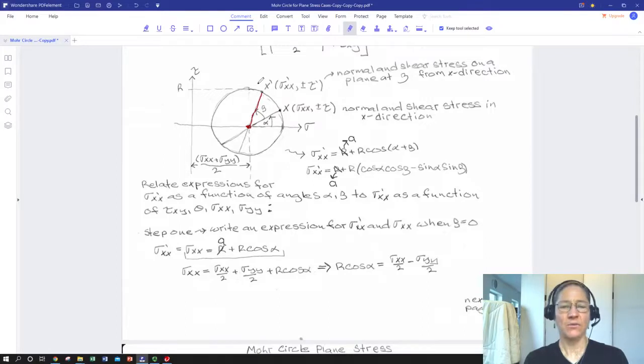If we draw a line from the circle center to the radius, and then we look at the angle that it makes with the x-axis, what we'll find is we're actually defining those angles of orientation of a plane that we could have with respect to the x-axis, you know, out on the body.